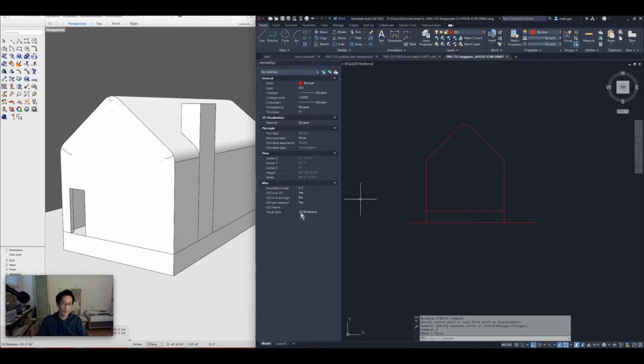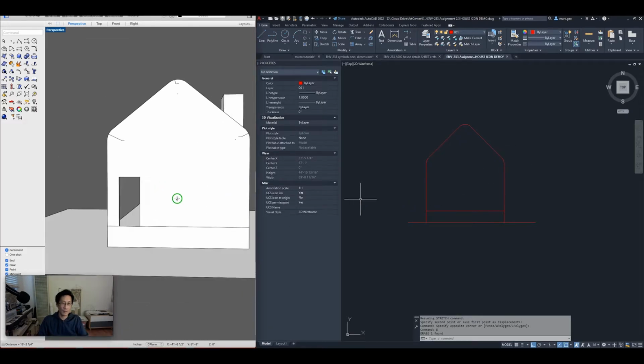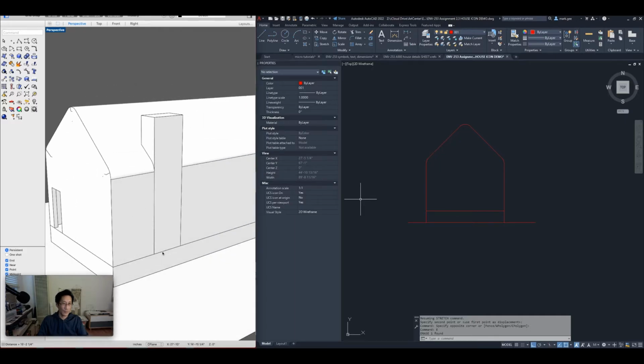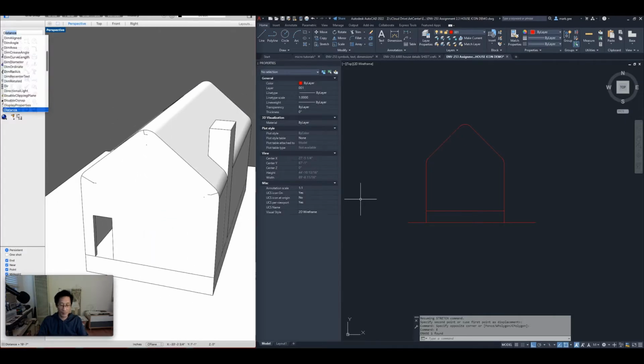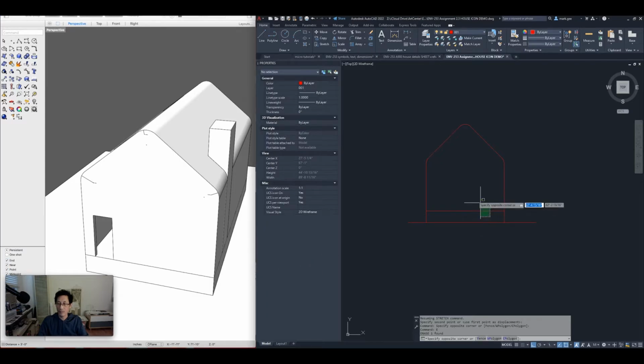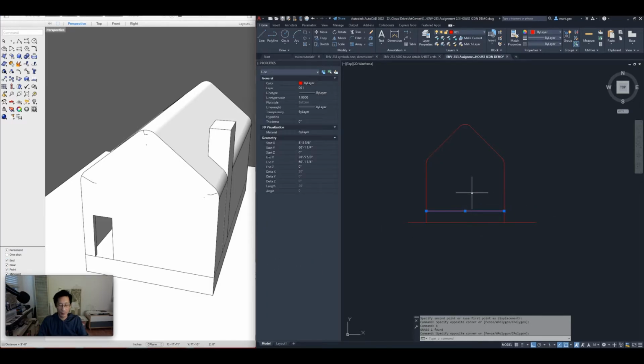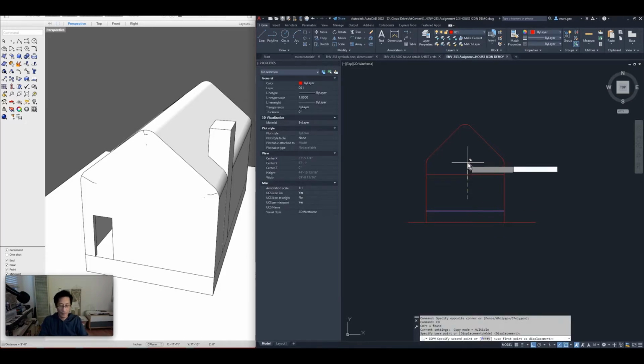Now let's draw the chimney in this elevation. And so we want from this, let's measure it from this point here. And that's 19 feet 7 inches above that line, our floor line, and the width of it that we'll see, let's do another dimension here, is 3 feet. So let's go back to AutoCAD. So from this line, we want to go 19 feet 7 inches, so I'll do a copy of this, copy that up, 19 feet dash 7 inches there.